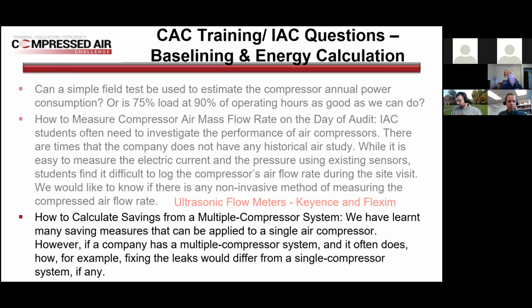Calculate system from a multi-system site. Yeah, this can be difficult. What I would suggest on multi-compressors is when you're measuring them, if you can data log them, it's the best bet to get all of them to sync up at the same time. Another way you could do it is if you have multiple load unload compressors, if you can base load them and then use whatever the load unload characteristic of the swing compressor is. That's really the ideal way to run a compressed air system anyways, is to have most of them base loaded.